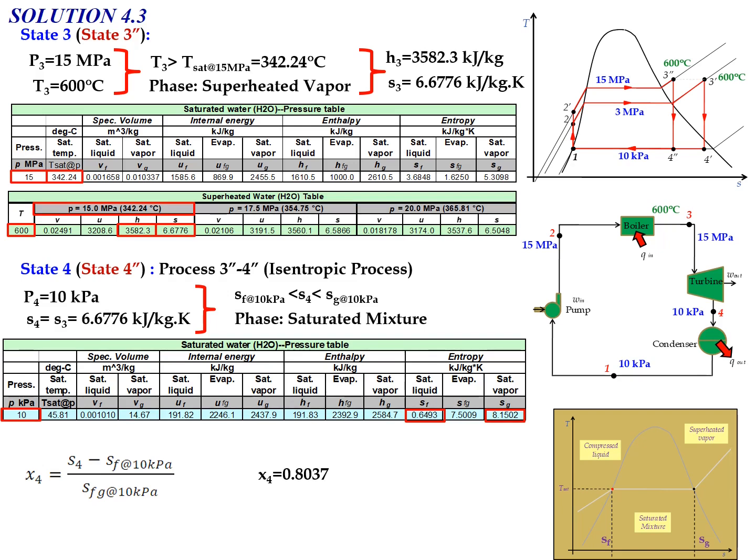If you compare to question B, the quality of the steam at state number 4 for question C is decreased. The moisture content will also increase. And use the enthalpy formula to determine H4.